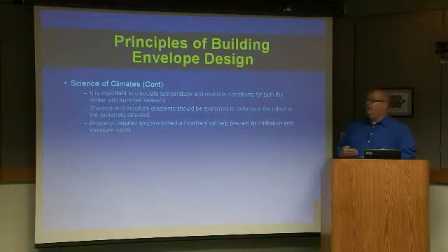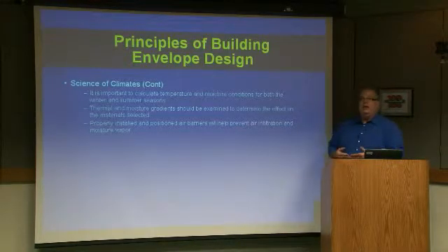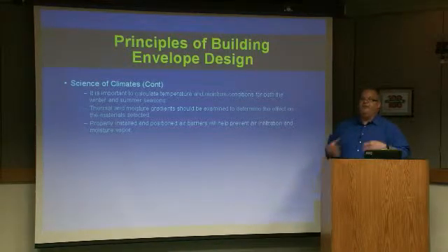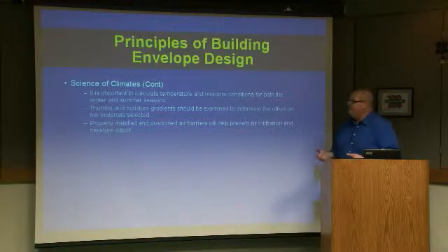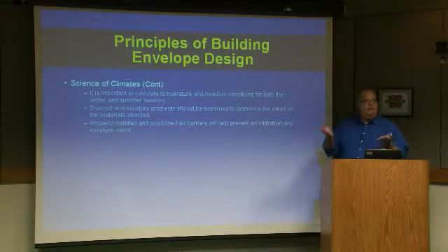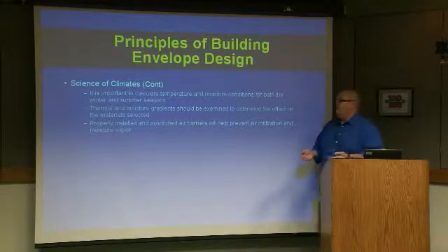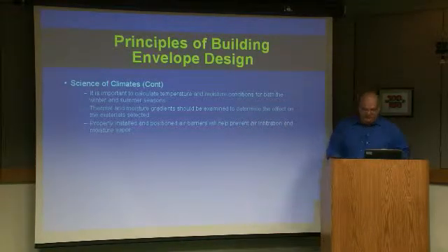In general, though, what we try to choose out there now is we see vapor permeable air barriers. Air barriers around 5 to 10 US perms. Fluid-applied, trowel-applied membranes that conform to the surface and are somewhat breathable. For most of the US, with most types of construction, 5 to 10 US perms, water vapor permeance for the air barrier, is a really workable number. It works very well in general. There are specific instances that might want one higher or lower, but in general, that's a pretty good rule of thumb.